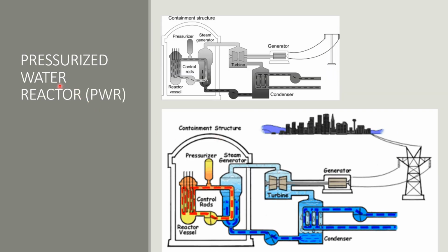So we have pressurized water reactors. In this, we use a pressurizer, and unlike boiling water reactors, the water inside the reactor does not convert into steam. We use the pressurizer to increase the pressure of the water, so that the boiling point of the water increases. After the reaction, due to high pressure, the very high temperature water is present inside this red line.